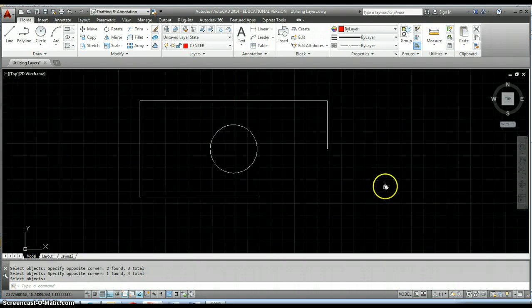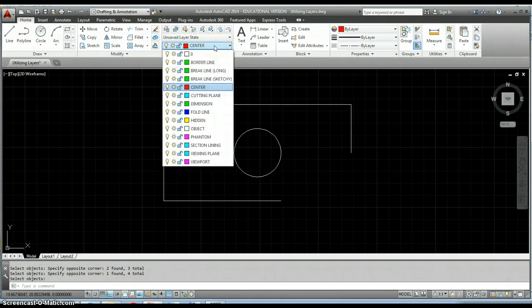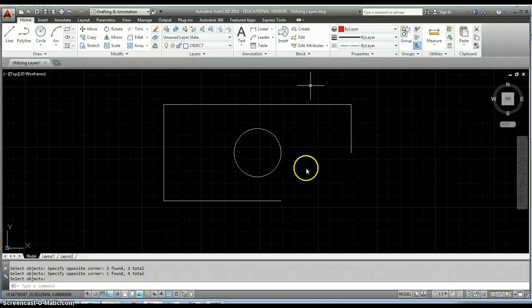Once you find that problem 3-28, that little isometric view of this little block, go ahead and draw it as much as you can. Before you start drawing, you're going to want to set your layer current. That's really the best way to go about using layers: whichever layer you want to draw your items on, just choose that layer out of this list before you draw. For instance, I'm going to set it to the object layer, and then I'm going to draw this angled line in that I've got left.